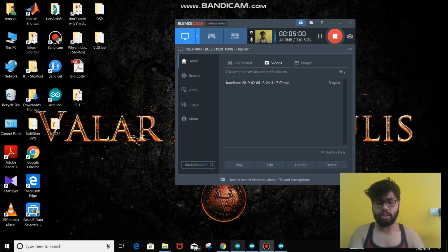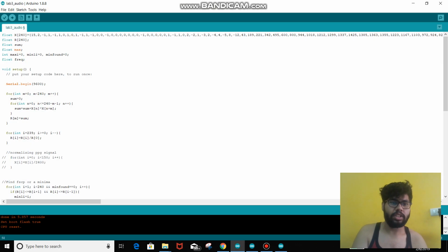Now to find the pitch frequency of an audio signal. The audio was recorded at 8000 Hz sampling frequency, and for 1 second. The audio was in .wav format, and we have translated that into a .csv file by using Python. Now we consider a frame of 30 milliseconds. That is why we take 240 samples and store that in an array X.